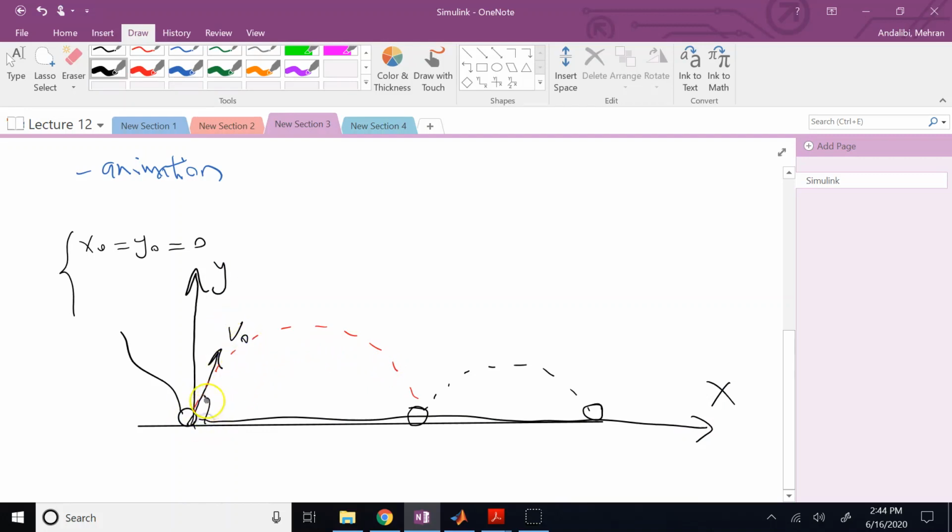Then my initial launch velocity is v0, which you determine, and my initial launch angle is theta naught. Right? So this is how you set it up. Good. Now, when it hits, and again here you have to provide another set of initial conditions, you reset it. How would you reset it? Because here you have to provide again x0 to the Simulink, a y0 to the Simulink, a v to the Simulink, and a theta to the Simulink. How do you do that?